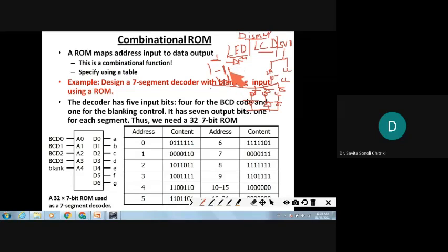So I am going to send 1 1 in common anode, and in common cathode I will be sending 0 0. This was what my question was. Alright? So liquid crystal display itself is different. So to do all these things, what is the code to be sent to display each number? Again, you need a driver IC for 7 segments. So here the 7 segment will be there, and the driver IC will be here.